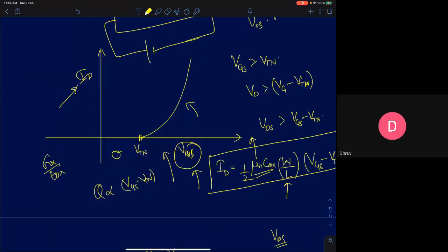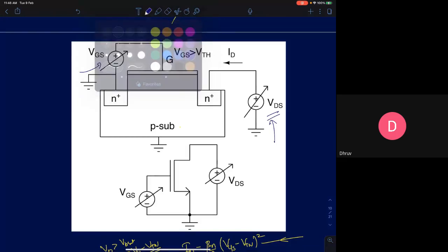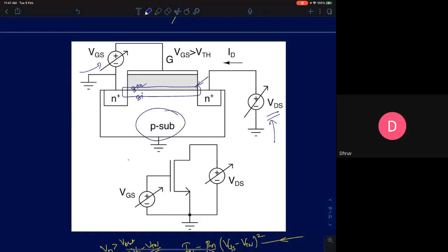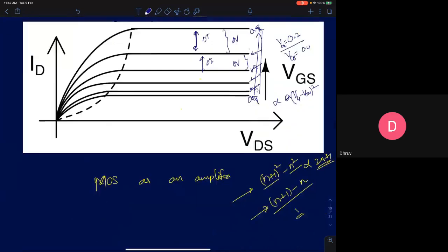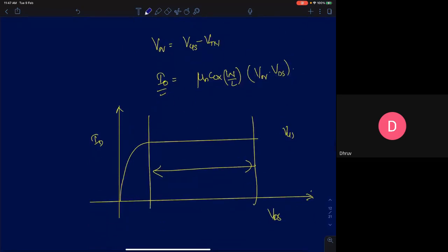But in a MOSFET, it's not a pure semiconducting region. It's actually the surface; the electrons are moving near the surface. Here this is silicon dioxide, this is silicon, so there is a sudden change at the silicon dioxide interface. That mobility will be slightly different from your bulk mobility. If an electron or a hole were traveling in the bulk region of a semiconductor, that mobility will be different from the surface mobility. We'll talk about that a little later. I'll quickly finish this lecture and then take 2-3 minutes to finish it.